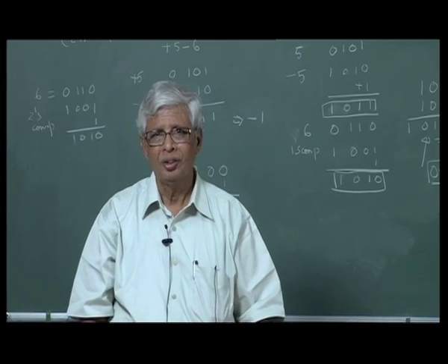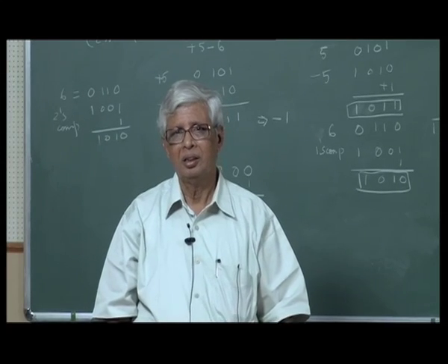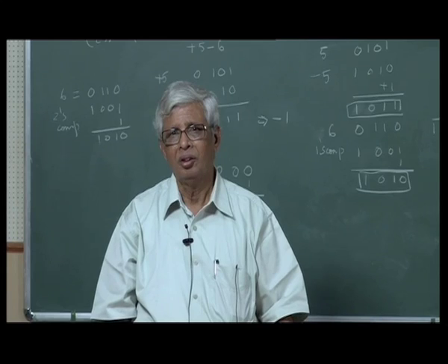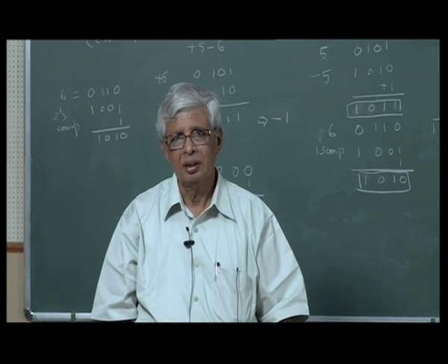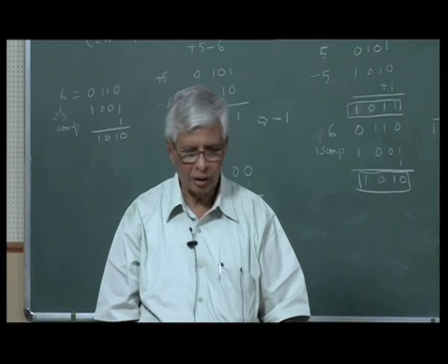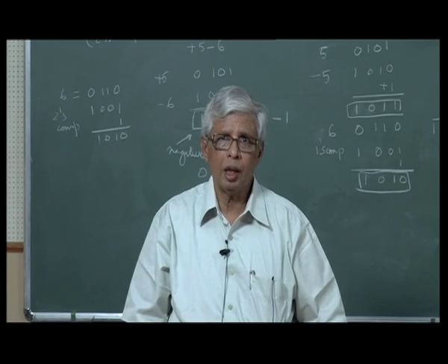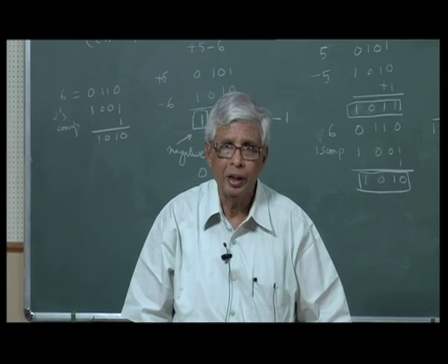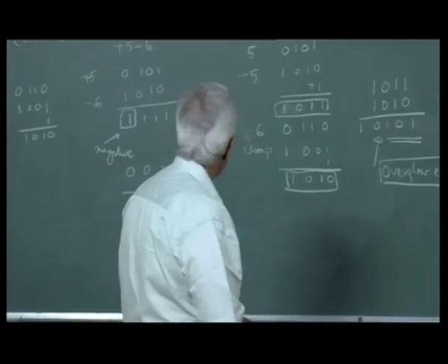My question is, wherever we see a negative number, we take the complement of it. Instead of 2's complement, if I take 1's complement, will there be a difference? Yes, definitely, because 1's complement and 2's complement are not the same. 2's complement is 1's complement plus 1. So that 1 has to be added somewhere. I will tell you how to do that.